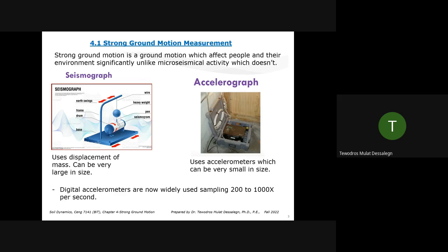The drum moves, then this pen scratches on the paper, and we get that recording. This is the old-days analog way of recording the seismic motion, and it uses displacement of a mass and can be very large in size.